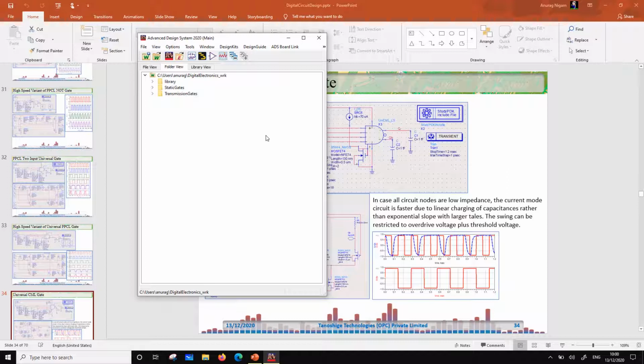Flip-flops, right? They are going to be edge triggered. So if there is a clock that has two edges, the rising and the falling edge, you can have a negative edge triggered flip-flop if the transition takes place at a falling edge. If the transition takes place at the positive edge, it is called positive edge triggered. In case of the latch, the transition can take place during a certain level, which may be a positive or a negative level. So the difference between a latch and a flip-flop is that a latch is level triggered while a flip-flop is edge triggered.